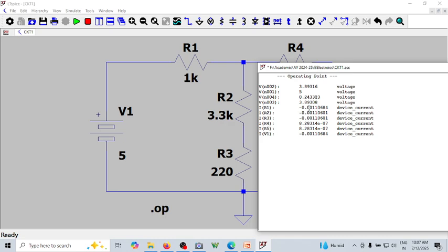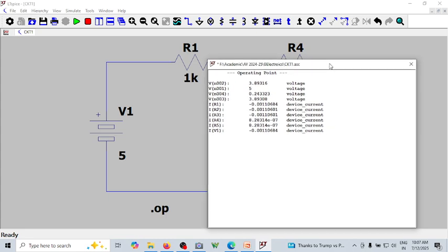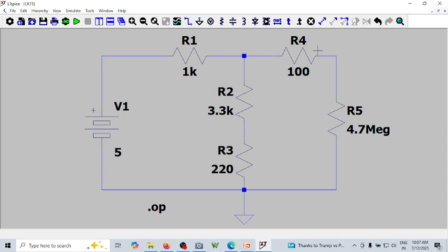You may be wondering, okay, why is this current negative? Some currents are negative, some currents are positive. It is only because of the way you place the component. I can make this negative current positive, or this positive current negative, by rotating the component. So what I'll do is I will select this component. How do I select the component? Can you see there is something called move? Just click on this, just hold this. Let me simply say rotate. Control R twice. Let me place it now.